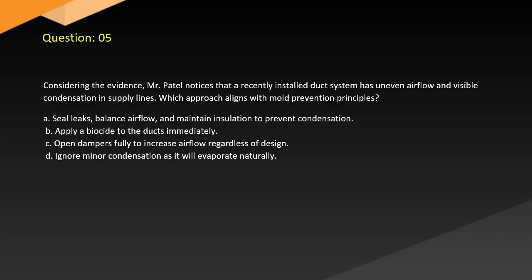A. Seal leaks, balance airflow, and maintain insulation to prevent condensation. B. Apply a biocide to the ducts immediately. C. Open dampers fully to increase airflow regardless of design. D. Ignore minor condensation as it will evaporate naturally.